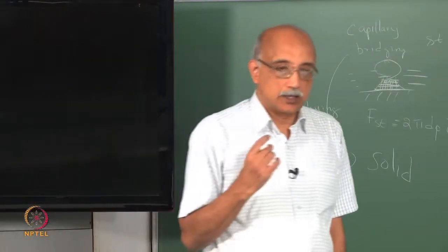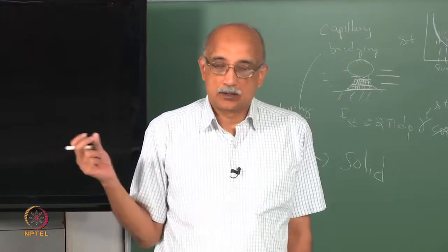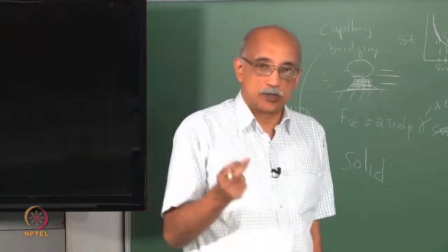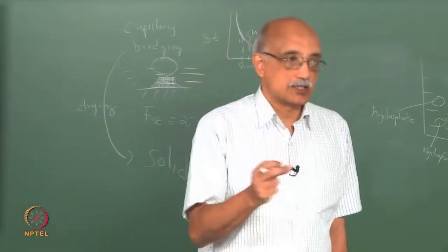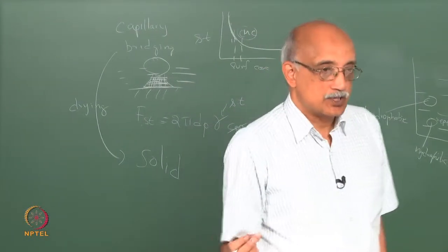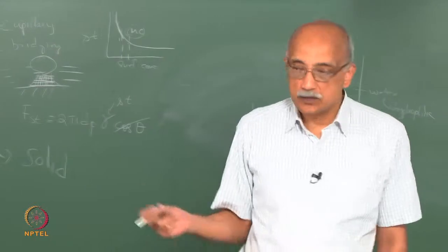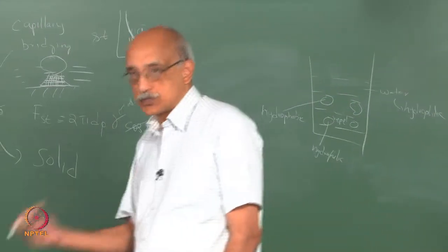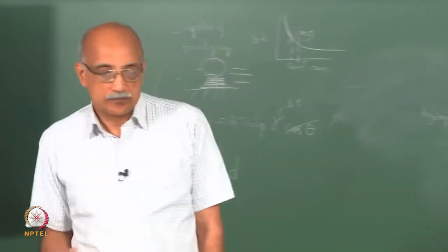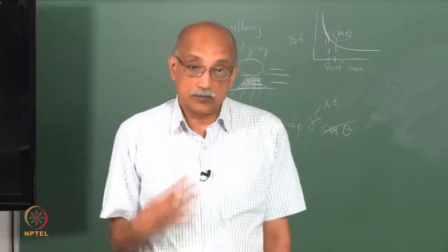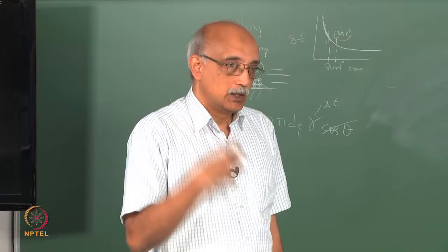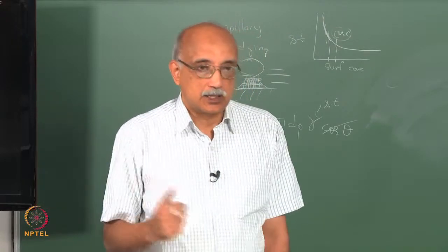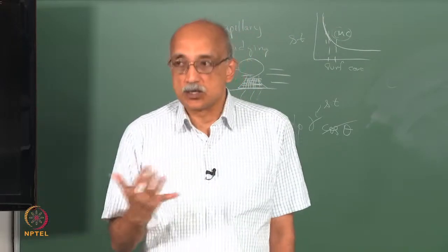In particular, it affects pressure drop, and process engineers are always worried about pressure drop, because pressure drop has an immediate impact on the cost of the process. The higher the pressure drop that you have to deal with, the greater is your processing cost. So, a process engineer would always like to minimize pressure drop so they can pump more fluid through with a smaller pump, and therefore the process costs less.